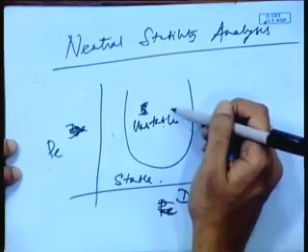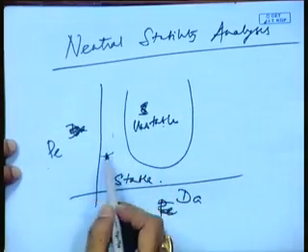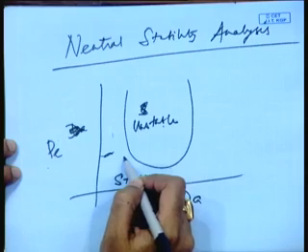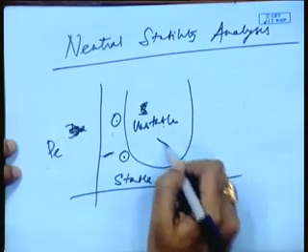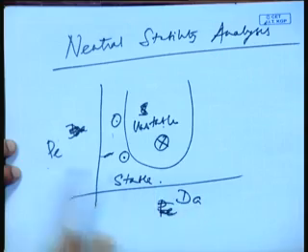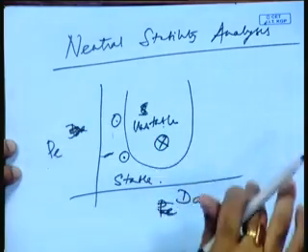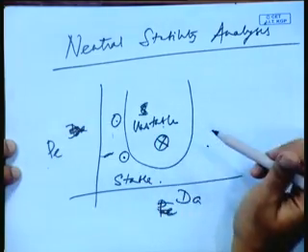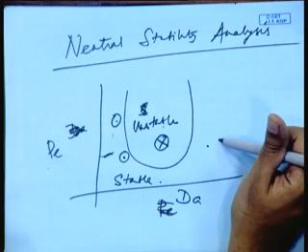So, if you look here, essentially you choose your Peclet and Damkohler such that your system stays here or here or here and does not go here, anywhere here. Okay, so that's your aim. So you can directly choose the parameters. You don't have to do calculations all the time. Once you get the neutral stability curve once and for all, you can directly choose your parameters and make sure that it's in the stable band. So that is our aim, not to just solve one problem, not to just solve for the steady states and analyze their stability, but to get a neutral stability curve so that you can use that at all times. Okay, so that is what we are trying to do over here.